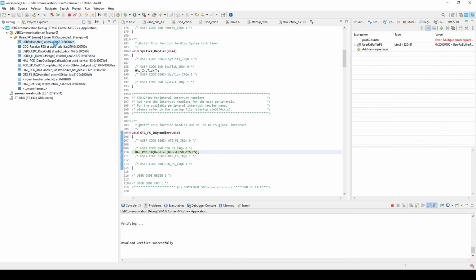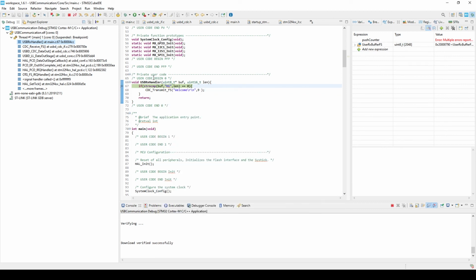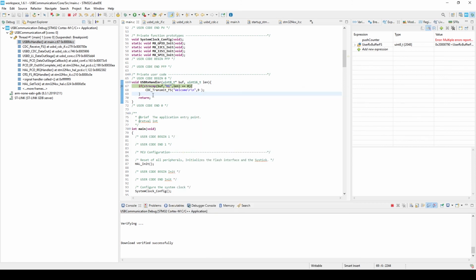But what you have here is a function. For now, since it's a really small function, it's fine. If you write tens or even up to 100 lines here, then as you add more lines of code it will take more time, and probably at some point it will hit the limit that you have to handle an interrupt. It will cause a lot of problems: a hard fault handler, or the USB stops responding, and it can stop your application from running.